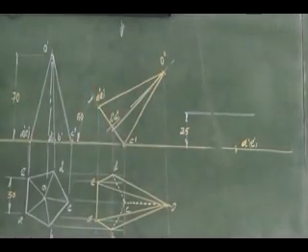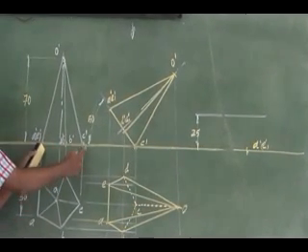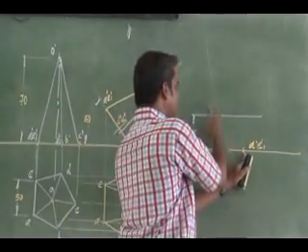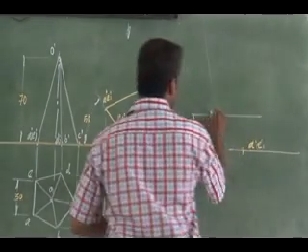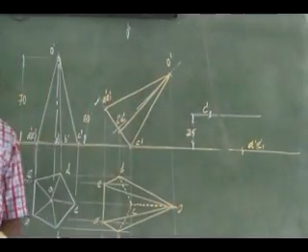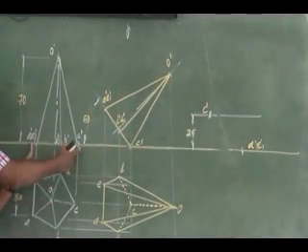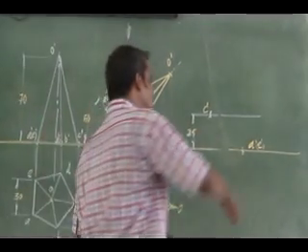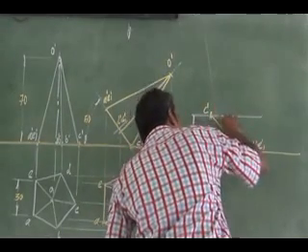Right. Now what I can do is measure the length of the base in the front view, that is the A to C distance. That distance I can measure in my compass. From A to E, I can cut it to the locus. So this is going to be my C dash. Now is it clear? The A to C distance of the front view will be marked on the locus. C is marked on the locus. Now this joining will give me my base.